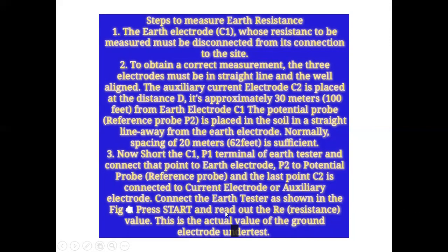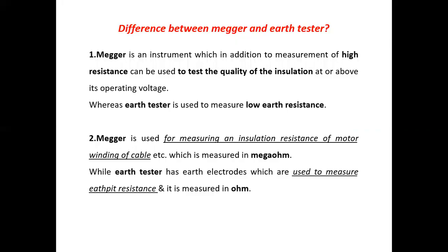Press start and read out the earth resistance. Sorry, read out the RE, that is the earth resistance. This is the actual value of the ground electrode under test. This is the procedure to measure the earth resistance.